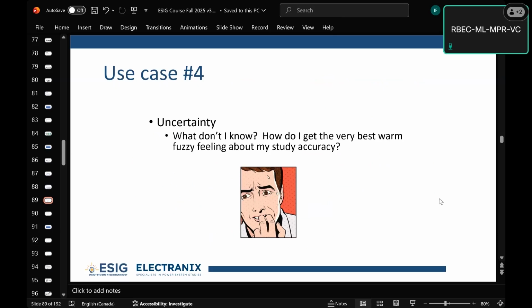And so they're like, I think you need to model all of that stuff too in EMT. And I'm like, that's going to make it really long. Let's try this rather. Let's add a co-simulation, see if it makes a difference. And if it doesn't, we'll just fix it there. And the customer was okay with that. And then you can sort of validate where the boundary of your EMT study should be, right? It gives you some confidence.